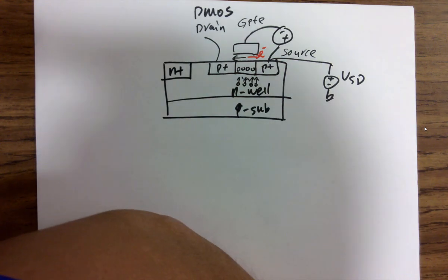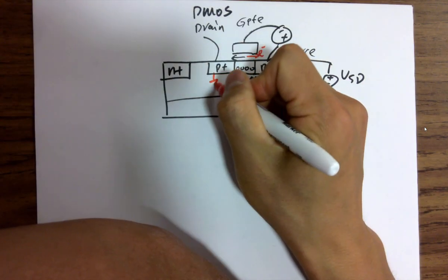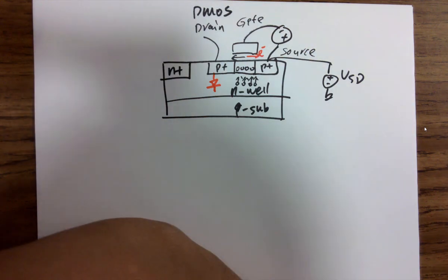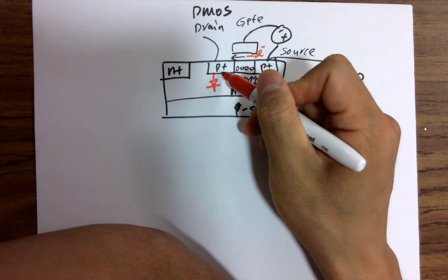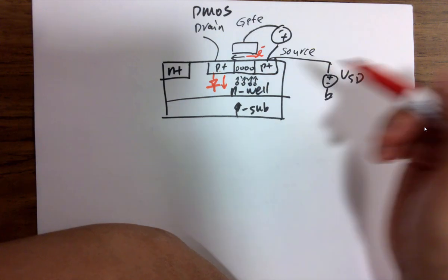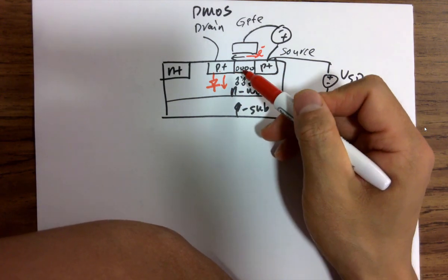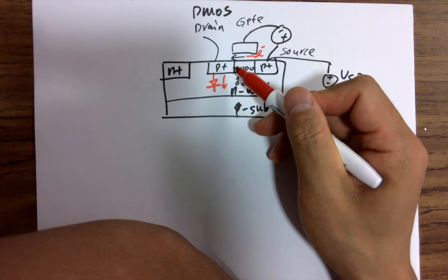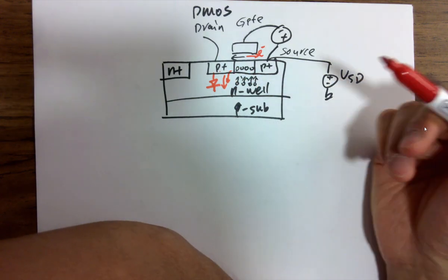Same concept. It's forming undesired diodes here. And if this accidentally becomes a higher voltage, it's going to conduct current, running current into the N well from the channel, and what's going to happen is stealing holes from it. So holes are going here, in concept, right?